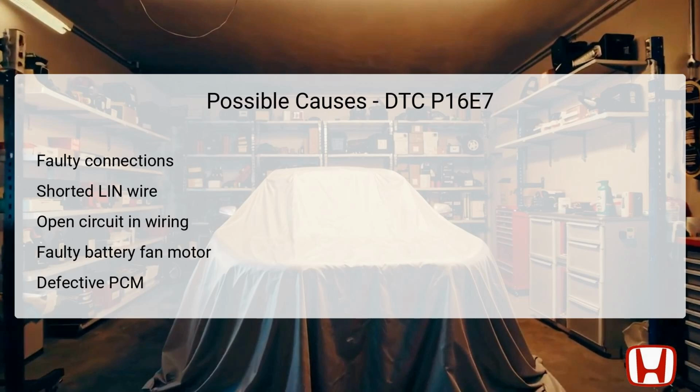error. The battery fan motor itself can also be faulty, leading to operational issues that trigger the DTC. In rare cases, a defective PCM could be the root cause, resulting in improper monitoring of signals. Each of these factors contributes to the malfunction, making it essential to conduct a thorough inspection and diagnostic evaluation.